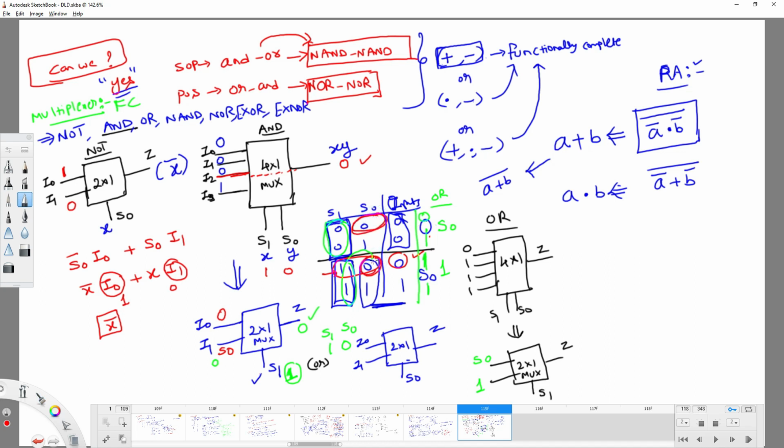When 0 0 is the input, what is the corresponding output you are expecting? 0 only, meaning that irrespective of S1, you get 0 again. What about the 1? If you have 1 1 as input, it looks like 0 1, the same output. So it will be S1. So now I0 is 0, I1 is S1. Similarly, these two are now equivalent.